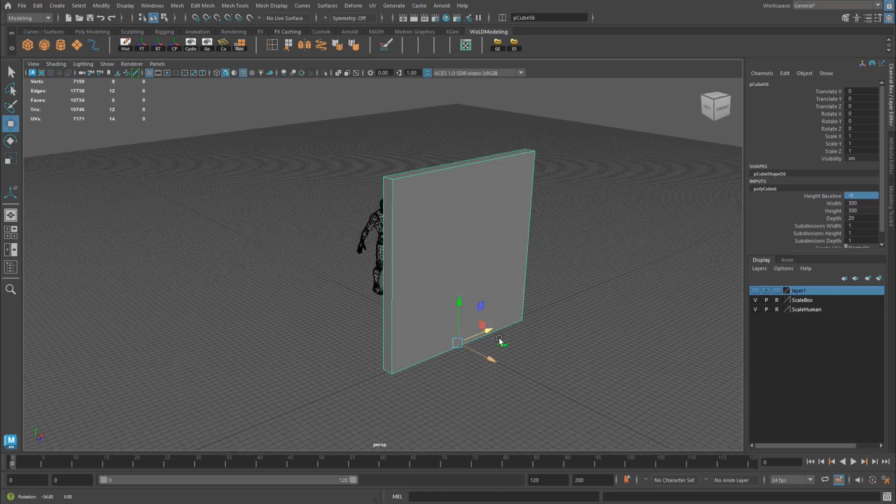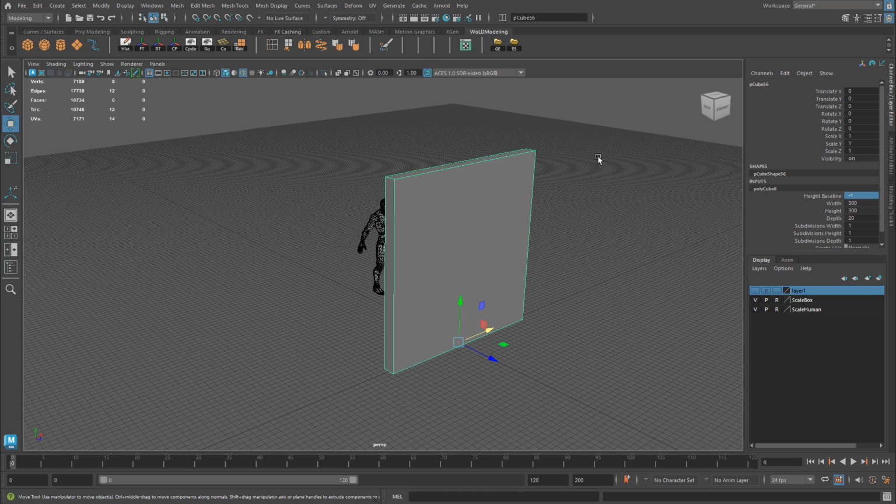And you should keep the wall, the floor, the ceiling, the window, and the doorway the same size. So that way they can be swapped out and they match. The floor will match to the wall, the floor will match to the ceiling, to the doorway. But I also don't know this measurement for sure because I just need to prototype it. And again, your sizes might be 400 by 400, maybe 300 by 400. Maybe you're building a larger environment, and in that case, it might be a standard wall size 500 by 500. So you're gonna have to test this out and establish that initial standard block for your modular assets.